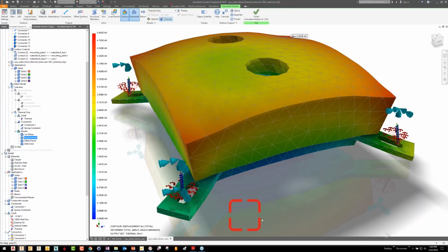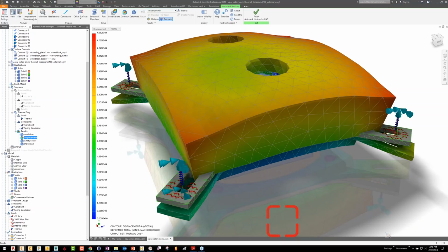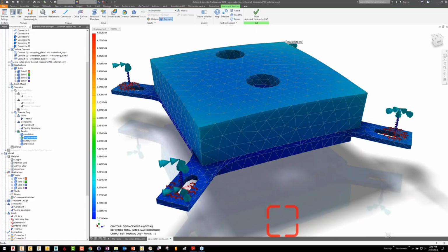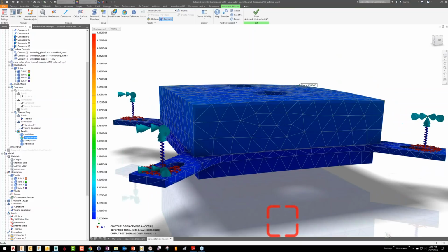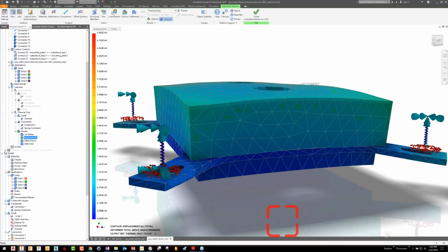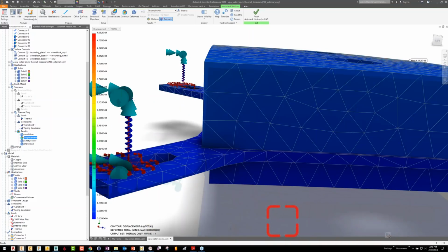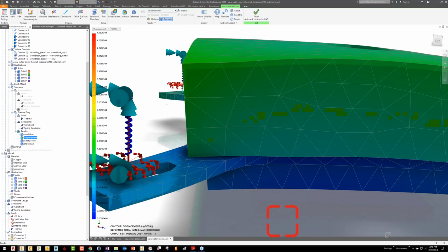Yeah. The displacements are pretty small overall, so the exaggeration tends to be kind of funny looking. But it does give you a picture for what's happening. Once you add it to the actual structural and the 12 pounds is involved, the scale of the deflection at the tabs is so much higher that the thermal expansion effects are much less visible, if at all. But this is just thermal alone, no 12 pounds on it, and you can see what we're looking at for potential thermal stress. Look how much more the acrylic block is growing compared to the mounting plate, right?